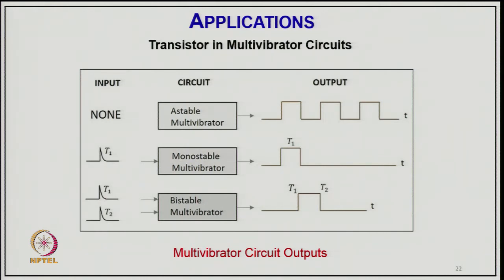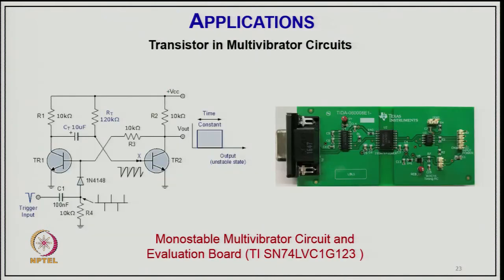So, these multivibrators again have transistors, and you can build the typical circuit with a couple of transistors, as here for the monostable. You give the pulse, and the duration of the pulse in the monostable multivibrator you can adjust. It consists basically of a couple of transistors, as you are seeing there, and they go on operating in toggle mode. Even both transistors can be in one single chip. Finally, there are a lot of chips available which have multiple transistors in a single IC chip.